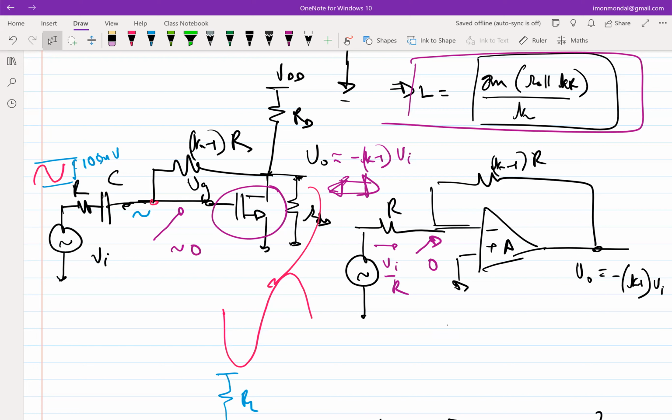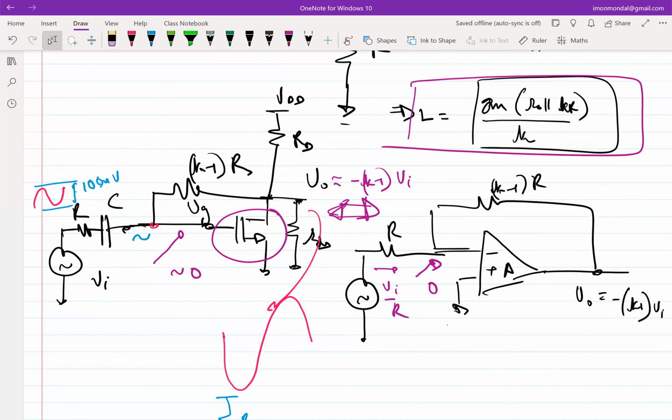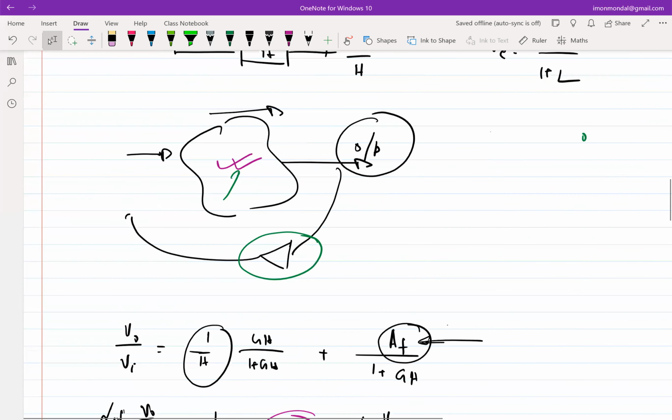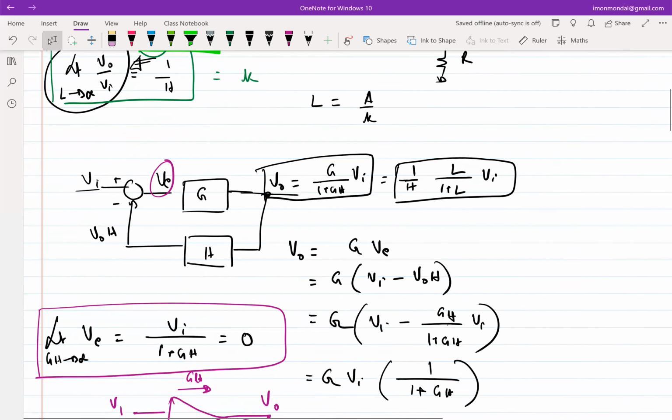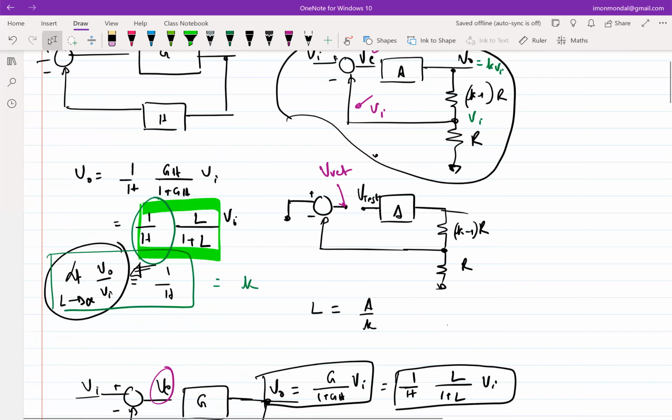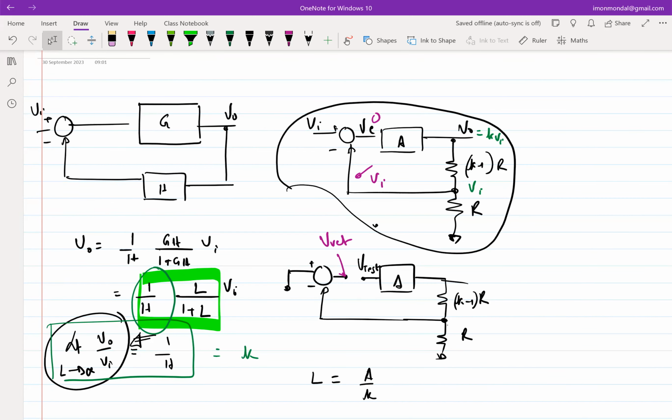So without knowing anything about the details of the circuit, can you tell me, in general, can we have a high impedance node in a negative feedback loop? Let's say so block diagram. Can we have a high impedance node anywhere in the negative feedback network if I inject any excitation anywhere? Assuming the loop gain to be infinite, very high.